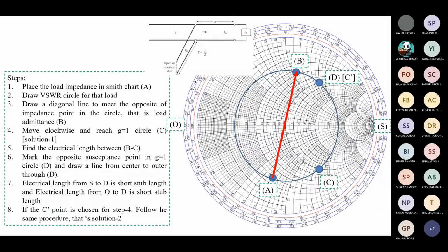And how to do it in the Smith chart. So the very first thing is we have to map the ZL. So ZL we have to normalize by Z0. You will get small zL. This small zL should be mapped first. So here you can see, assume that this is the point, small zL, and we have to convert the entire problem in the admittance mode. Then only we can easily add in parallel. Otherwise, in the impedance chart it is very difficult. So we have to convert this to admittance part.